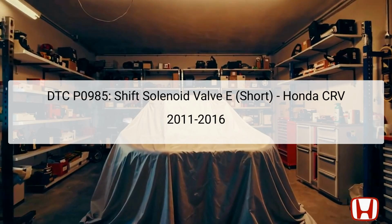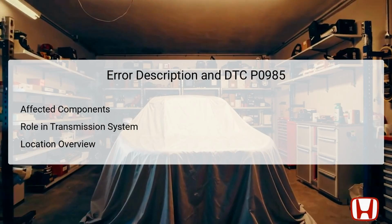The Shift Solenoid Valve E is responsible for regulating fluid flow in the transmission as per the demands of the vehicle's operation, crucial for proper gear shifting. When this DTC appears, it prompts a series of diagnostic checks using the Honda Diagnostic System, HDS, to isolate the source of the electrical fault. Special attention must be paid to the wiring, connections, and the valve itself to determine the root cause of the short circuit problem. The primary component affected by DTC P0985 is the Shift Solenoid Valve E, which plays a crucial role in the automatic transmission system.